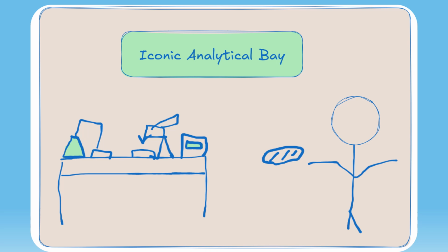Okay, so I made this video because I think the information is important. Let's say you're working in a clean room, or you're working with people who work in a clean room, and you need to take some measurements in an ionic analytical bay, as we can see here. And you're given a wafer, and now you need to see the resistivity for the device or just the material itself. That's what this video covers and what to take into account when using a 4-point probe.